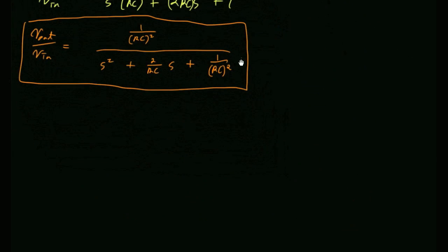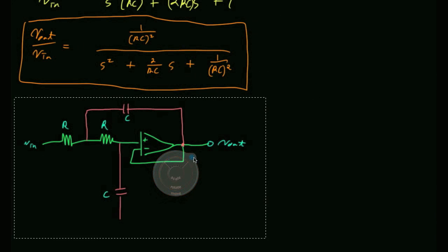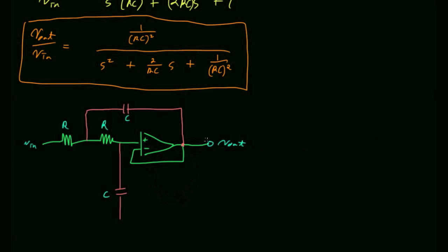What do you think? Can we use this circuit? Let's analyze this. Have I lied, first of all? Do we recognize, is this a second order transfer function? Yes. So what's going to be my omega naught? Sorry, your omega naught is 1 over RC, which is good. That's as we wanted it to be. What's your zeta? I mean, this term should be 2 zeta omega naught, right?